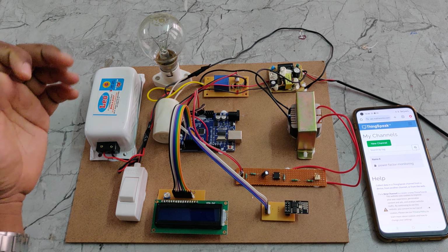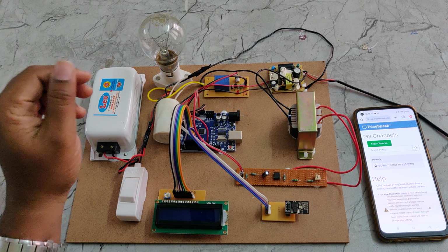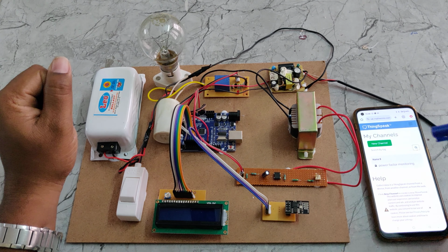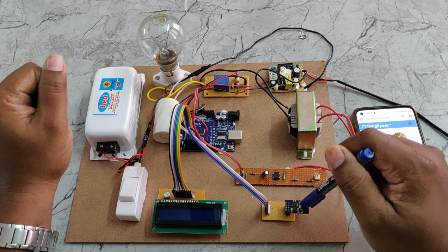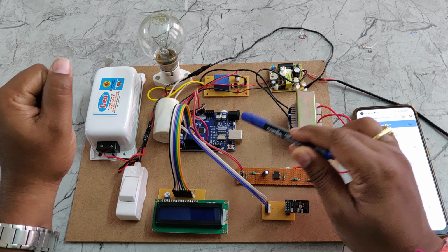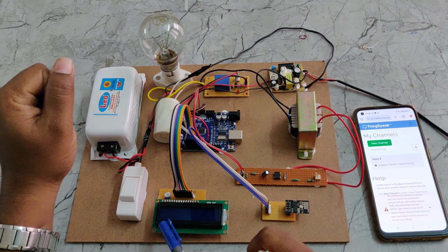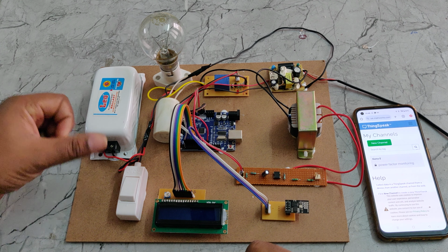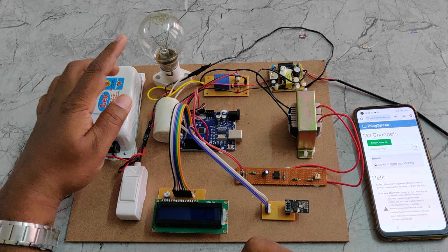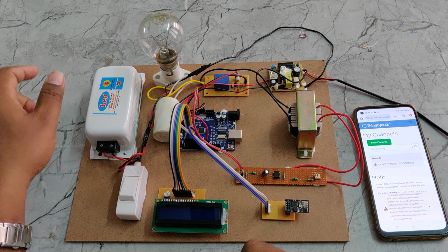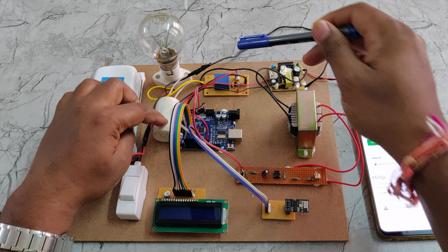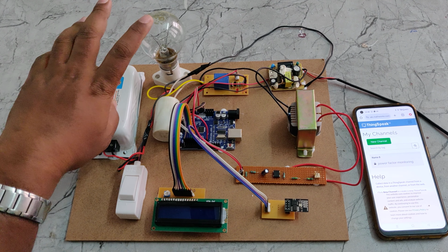And this operation is calculated and successfully executed by our Arduino UNO board. Also, in parallel, we upload the data to ThingSpeak with the help of this ESP8266. Voltage and current waveforms are captured by our Arduino UNO board, and the status is continuously displayed on the 16x2 LCD screen. And this is a switch to connect the resistive load in series with the R load and disconnect it. The capacitor is placed in series with the relay, in parallel to this R plus L.